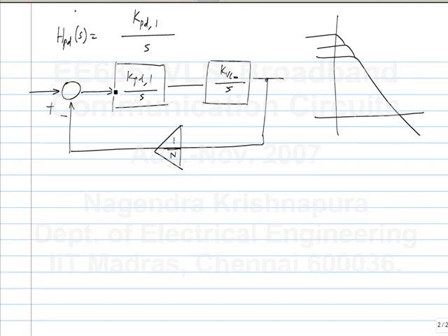Now because it's an integrator, it has infinite gain at DC, so it can support a control voltage at its output with 0 input, right? An integrator's output can be non-zero with a 0 input. Okay. So will this work? This is unstable. Why? Because there are 2 integrators in a loop and it is unstable. Okay. So how will we deal with that?